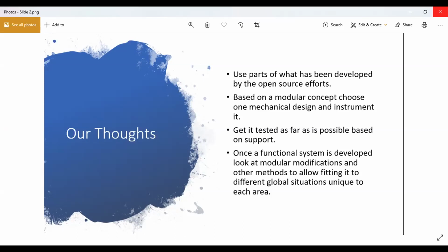With instrumentation, if we treat it like a bellows, we won't be able to calculate volumetrics based on deformation. We'd have to measure that directly. But we can get to the point, as Don said, with full instrumentation, no matter what is at the heart of the machine. And we've selected the Israeli design because that was the first full set of prints available. We likely will tweak a few things. I haven't studied them in depth, but if you just turn the ambu bag into a bellows, as Don said, it's got a few features in it. It's got some valves that you can take advantage of. You may have to put flanges and things on.